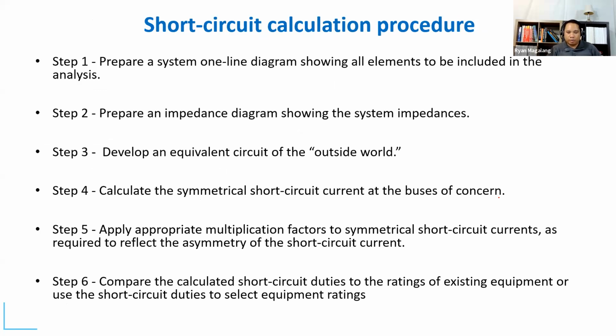Which are the steps for conducting short circuit calculations? You have to prepare your one line diagram. Obviously, you may have to conduct a site audit if the installation is existing. Well, you may have to go to the site and gather information, especially with the old installation where they don't have drawings. It's challenging to do that.